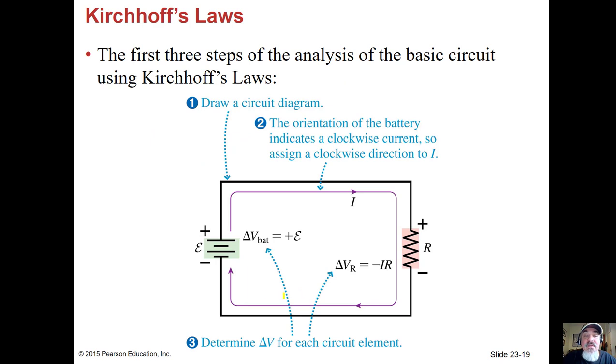So the voltage of the battery, the squiggly E, where does it go? Well, it's utilized here in this resistor. From Ohm's law that we did before, this is I times R. So minus to plus, and then plus to minus. Whenever you're going from a minus to a plus, you think of that as a positive quantity. Whenever you go from a plus to a minus, you think about that as taking something away. Okay?